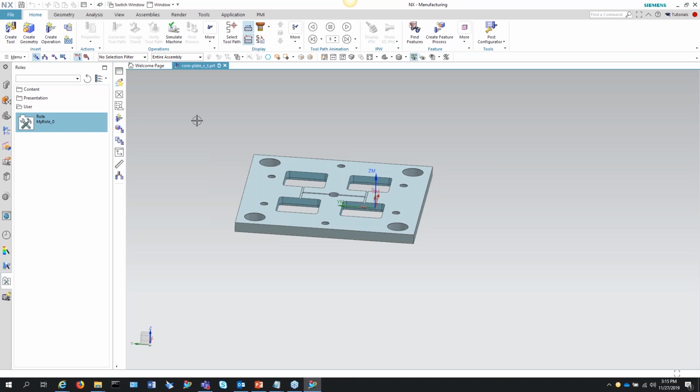The purpose of this is to be the most efficient that you can be as you're programming your daily tasks. So if you don't do turning, then remove show 3D IPW, and on the turning side of things. If you don't use your toolpath display up here and you use it out of your verification, then remove this.